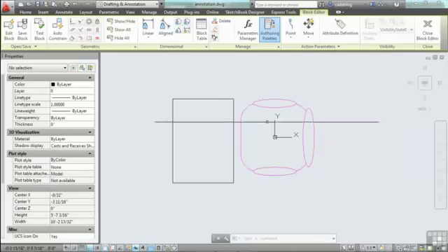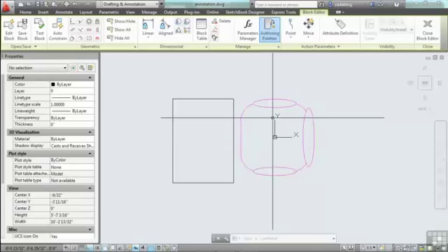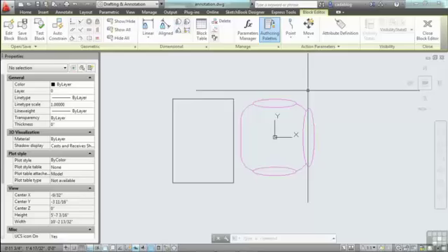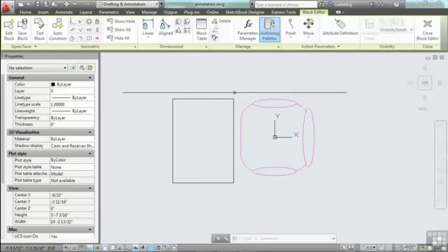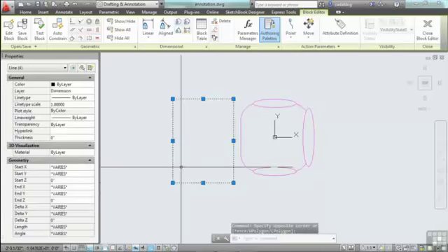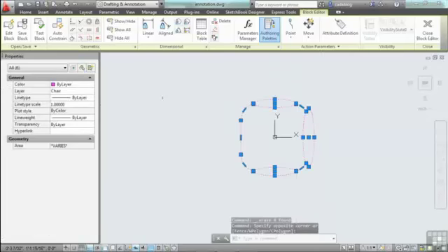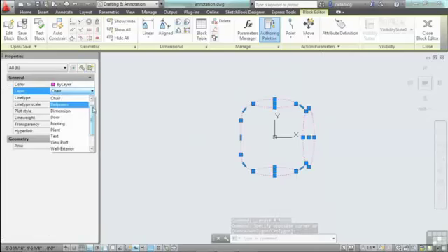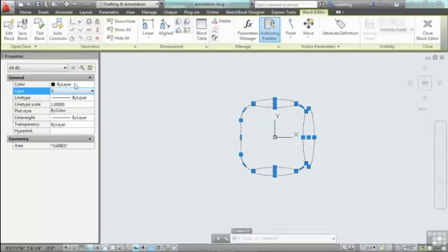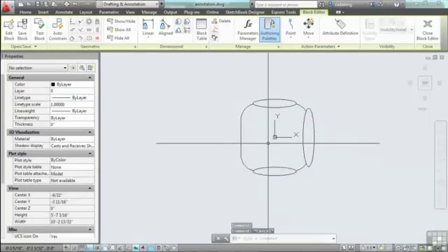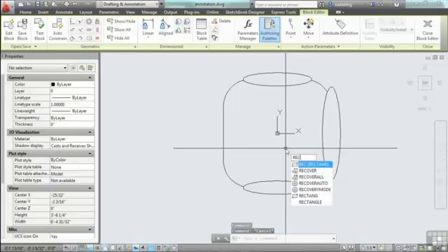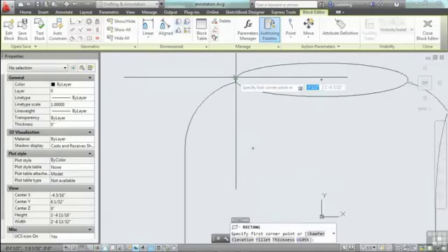Now we can make changes to all the line work here that we want, just the same way you would in a regular drawing mode. Now it allows you to edit this block without any other objects getting in the way, which is nice. We'll change the chair again. Let's get rid of our table, delete it. Let's put all of the line work here, not on the chair layer, but on layer 0, and make sure it's set to by layer.